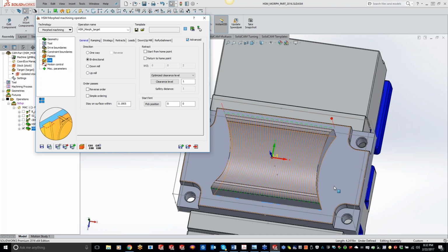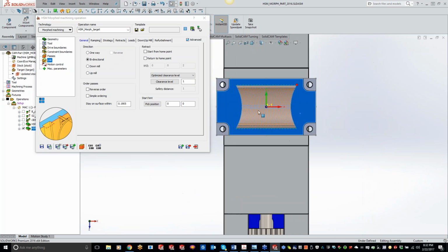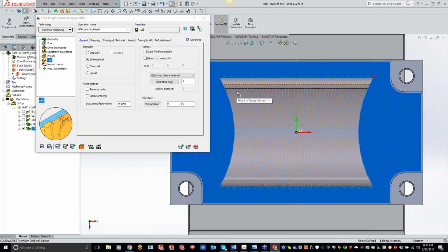So now is a great time to get a straight down view here, a great view of showing how the toolpath works. So like I said, it's going to follow that first edge that you told it, working its way around. And then as it gets to the center, we're going to straighten out our toolpath, and then it's going to start bending around for that second curve.